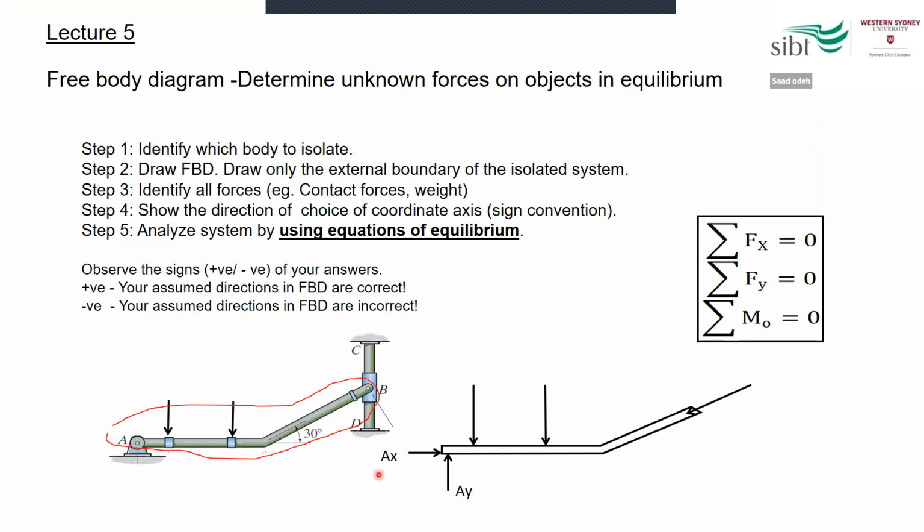When I complete the free body diagram similar to this one, I can start adding all the forces in the same direction together. So summation of forces toward Fx, summation of forces toward Fy, and the moment around a certain point, all these must equal 0. So when I apply this rule, I can find the unknown force or the unknown moment for any section of the system.